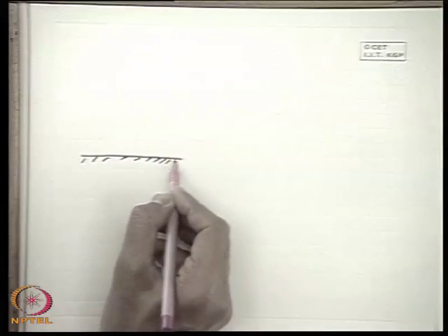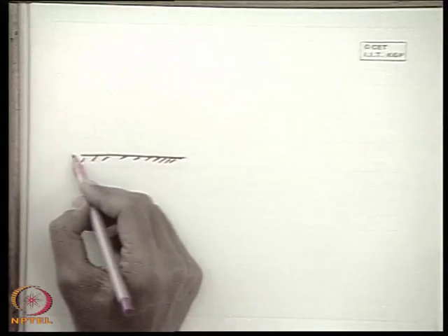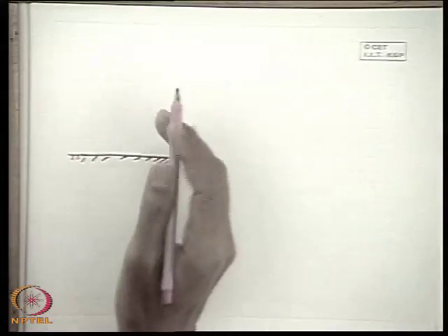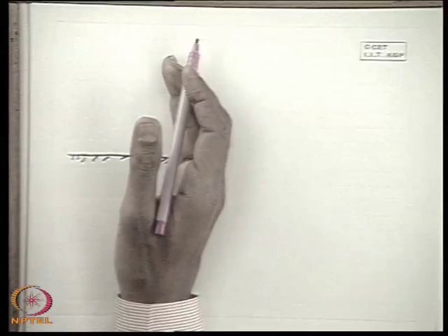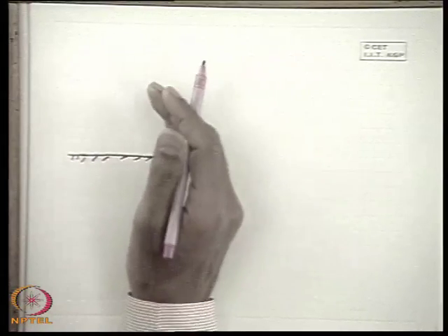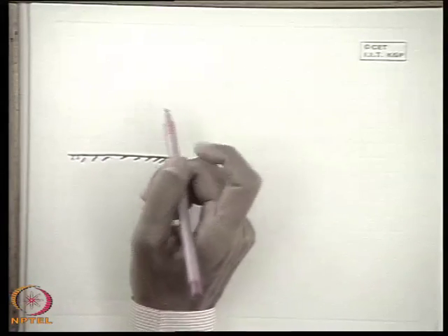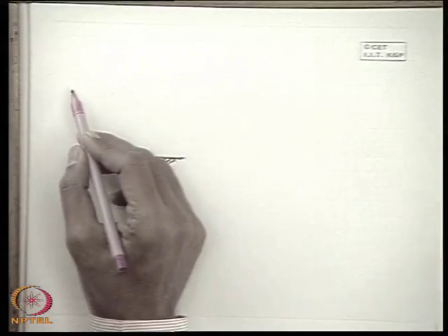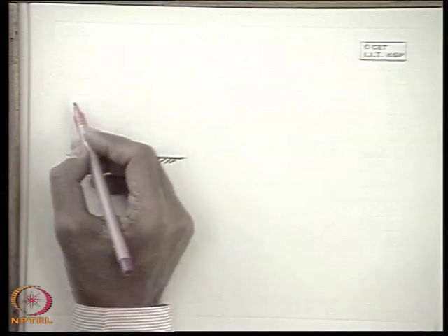Now you see, when the wave is moving through this channel, the region of the flow through which the wave has already traveled has changed its hydrodynamic parameters, like the flow velocity and the depth, whereas the upstream flow velocity and depth, which was the undisturbed flow, is yet to suffer a change.